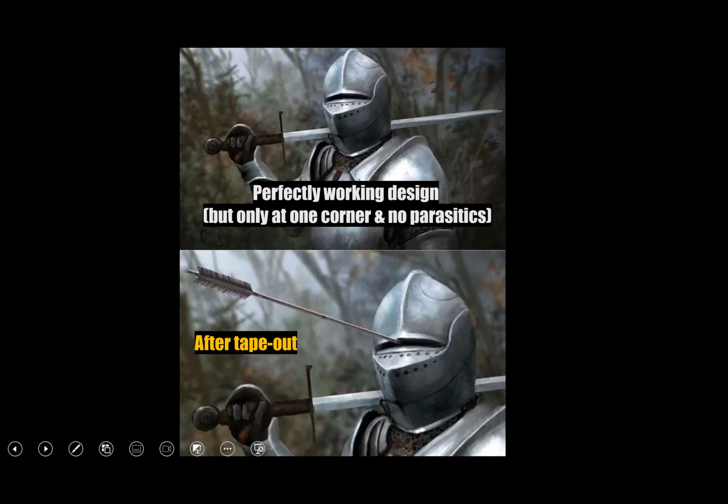And as I mentioned, with post layout parasitics, the simulation in practice can run for several hours or several days, right? So that is why you can't say, hey, I don't know what this transistor does, maybe I'll change this transistor 3-4 times, I'll run 10 different simulations and wait. No, then you have to wait for 10 years. It's not going to happen.